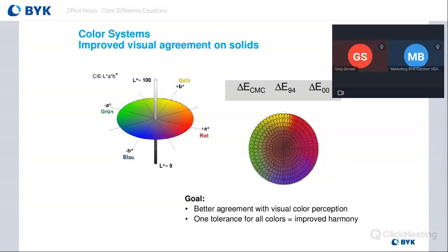Continuing with non-woven fabric material: if I wanted to make a comparison evaluation between different materials, is it accurate to use a color reader LAB and use a white and black sheet as background to make comparisons, with results in terms of delta E? Basically, what I want to measure is opacity, to evaluate how transparent the material is. Take the results of 2 different backgrounds and use the delta E. My assumption is that a lower delta E means the material is opaque.